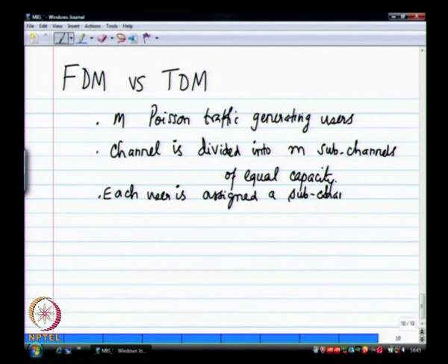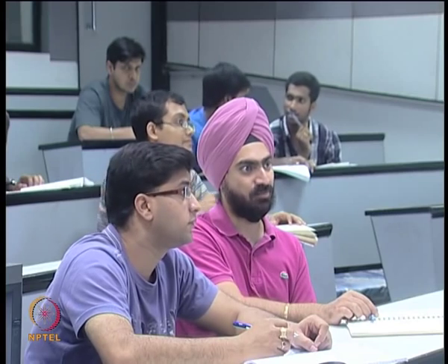So this FDM versus TDM debate has been around for a long time. Even today, some of our cellular systems are FDM. What does GSM have? For those who read WCN, what does GSM do? FDM, TDM or something else? It's actually hybrid, both FDM and TDM. You have FDM and then you have slots within each frequency, so you have this notion of a frequency that is then time shared.